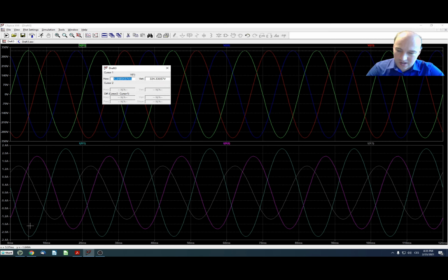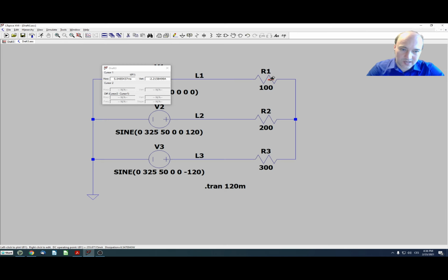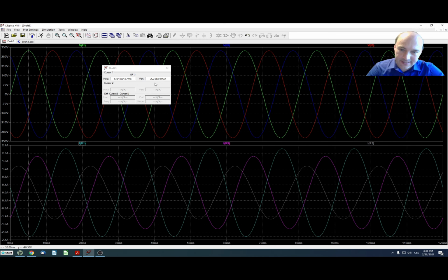And in the bottom half of my chart in currents, we can see that we have the current here, IR1, and it has also the magnitude here, the maximum value, but it looks negative. But again, let me repeat that this is only due to the fact that in LTspice the current probe here is pointing in the opposite direction than I would actually require in this circuit. So we can see that we have minus 2 point something amperes. Of course, it's a resistive load.